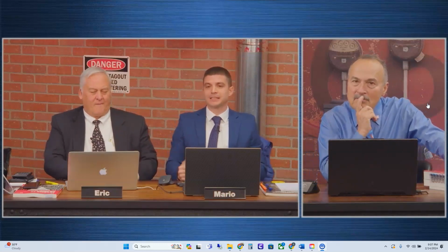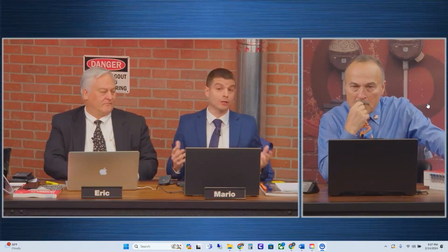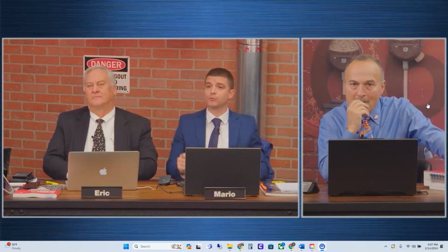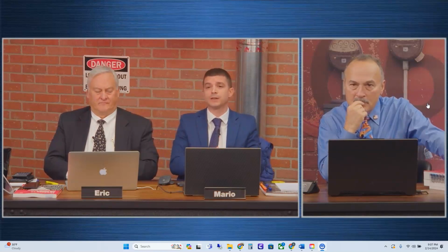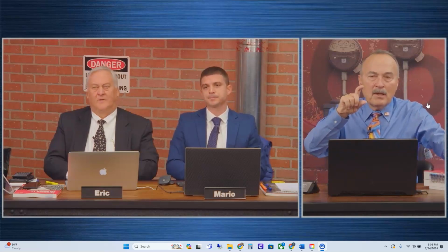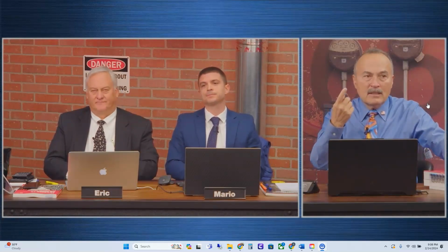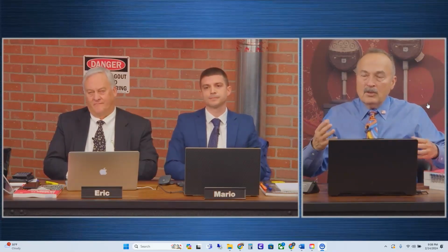And I just want to emphasize the key word Mike is using is equipment. You will maybe run across a scenario where you have equipment with 90 degree C terminals in it, but the equipment itself is still rated for 75 degrees C. And we're not looking at the lugs to see what the lugs are rated, because lugs are commonly rated 90 degrees C, and the lug guy sells it to everybody.